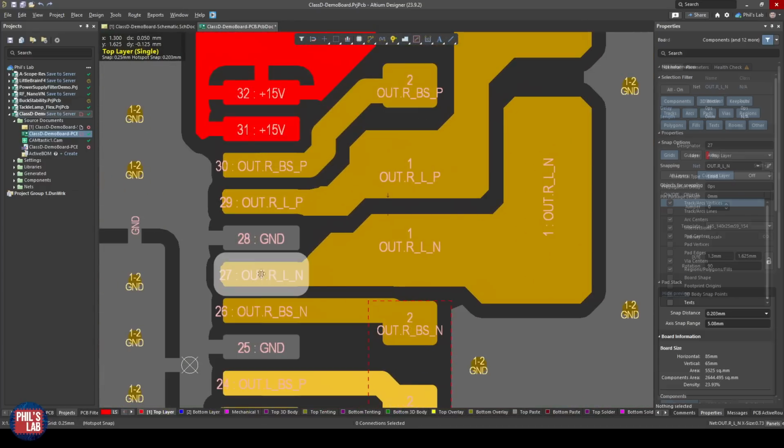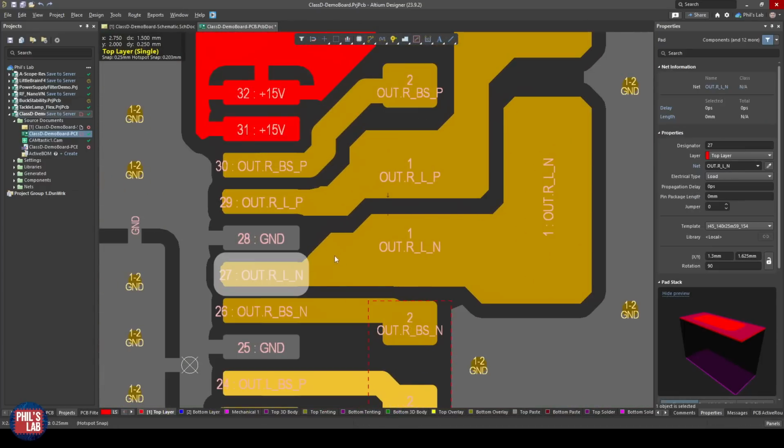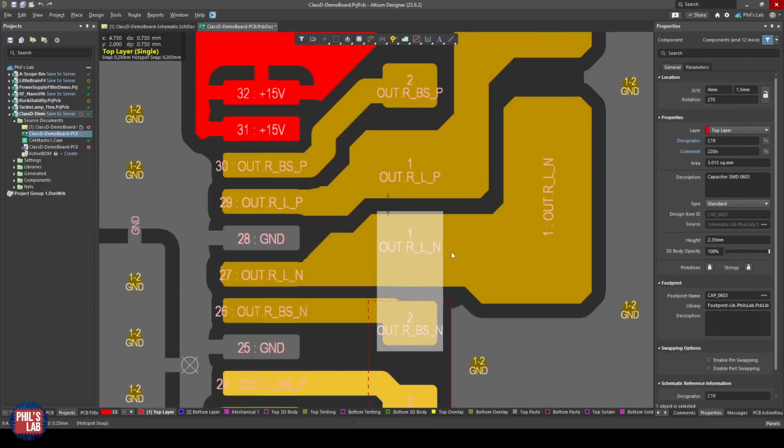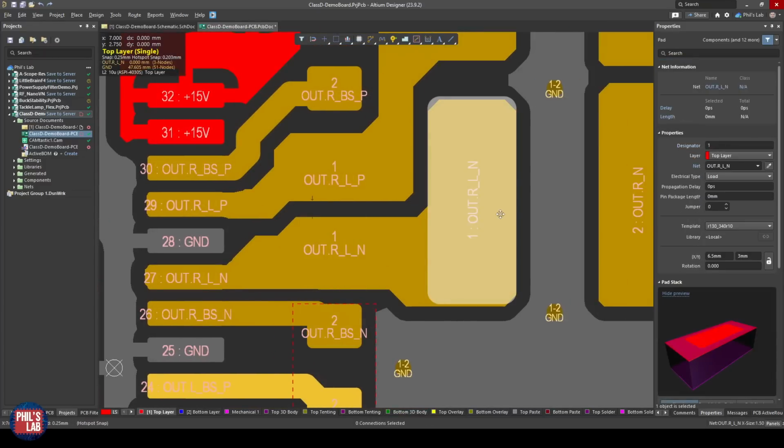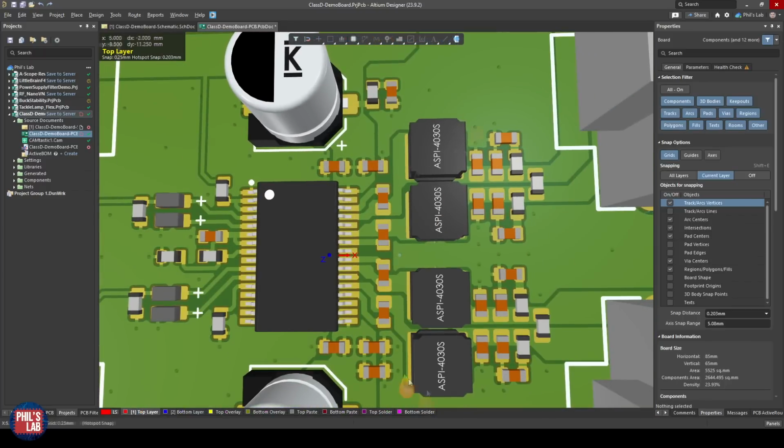Therefore, for example, for these switch node output pins that feed into the series inductor, I have a polygon pour that expands as soon as I get out of the trace. We need to size our polygon pour to be able to handle the maximum expected current without a significant temperature rise. Again, use the IPC 2221 calculator to help you do that, feeding into our bootstrap capacitor and feeding directly into pin 1 of our output inductor. You can see this connection is very, very short. It's wide enough, but not arbitrarily wide. And the same thing is repeated for all of our 4 output inductors and bootstrap capacitors.